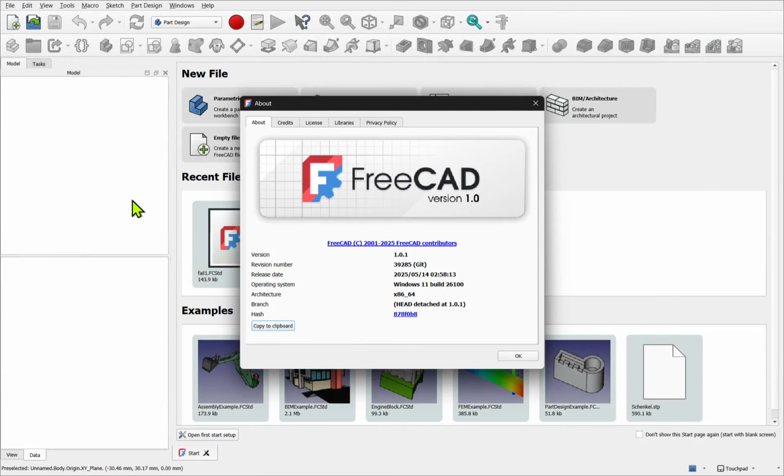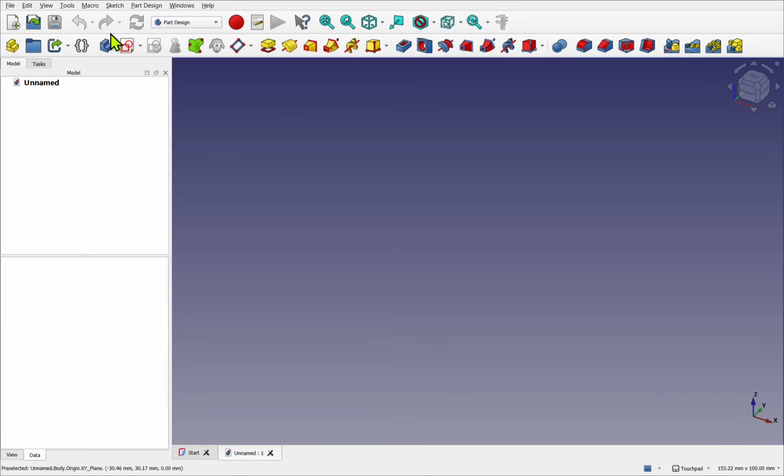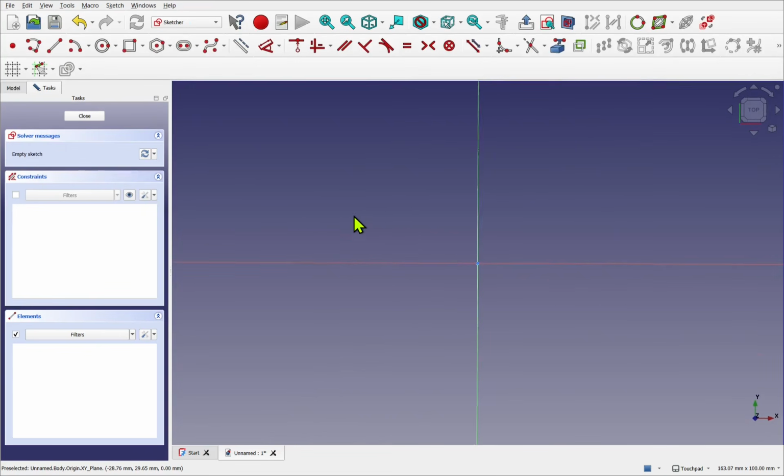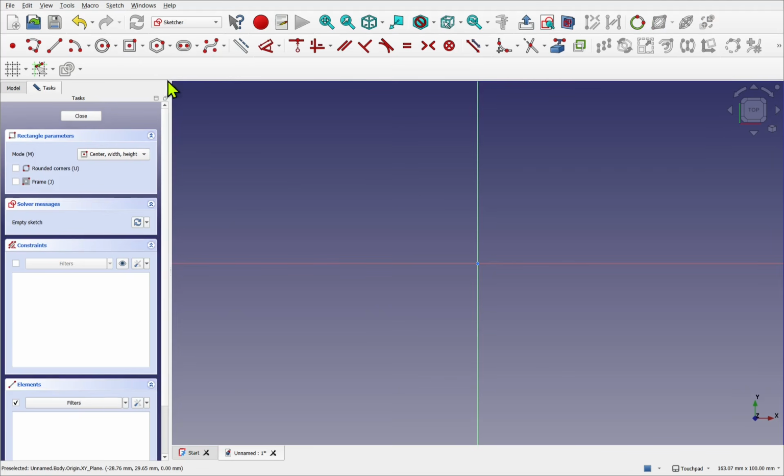So I've opened up FreeCAD and I'm going to start a new document in the part design, new body, and a new sketch. Start by building the basics, so the footprint of the brick looking along the XY plane. Let's use a centered rectangle by dropping down the rectangle tool and choosing the center rectangle within and sketching coincident to the center point. Click once, come out, and we'll drop a box in.